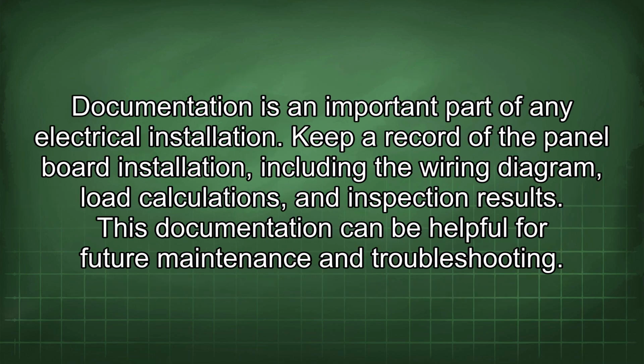Documentation is an important part of any electrical installation. Keep a record of the panel board installation, including the wiring diagram, load calculations, and inspection results. This documentation can be helpful for future maintenance and troubleshooting.